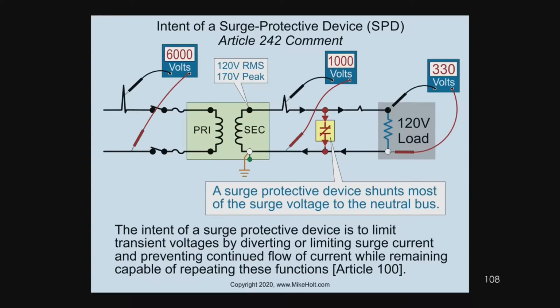There is no ground. And what manufacturers of surge protection devices will do is they say, well, we guarantee protection. And they say, well, we came out to your house and we measured your ground and you got a bad ground and surge protection. But watch this, Jacob. A lot of people, I would say almost everybody, thinks that a ground has an effect on the performance of a surge protection device. But it doesn't at all. Zero, nada. So what they try to do is say, well, we checked your ground. Look, you see this loose connection here on your ground? Well, there's your problem. No, the problem is that the product is not designed properly.